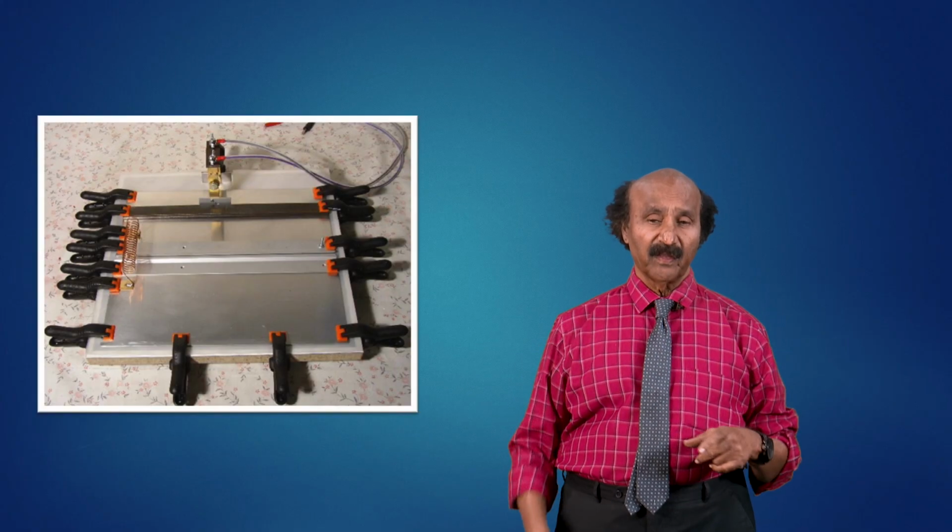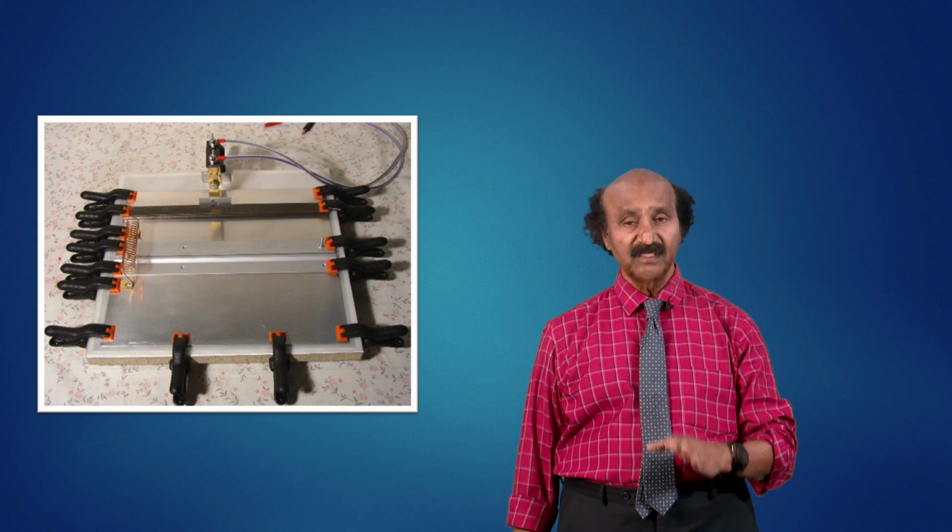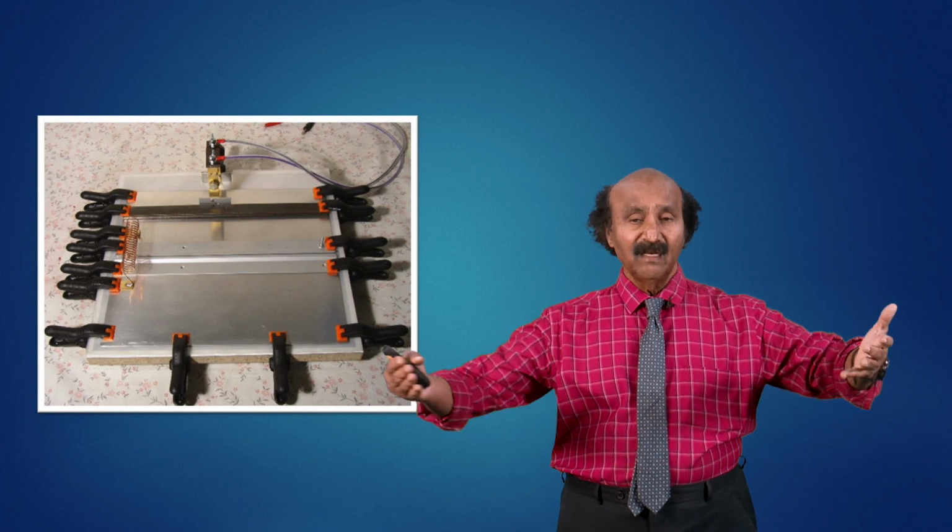You see there are two big sheets. It is true, there are two big sheets. These are thin capacitors. Here is one capacitor, another is a thin capacitor, which is very spread out, very thin. Since they are thin sheets, the inductance of this capacitor is very low. Because of this, when you produce a discharge, the current rise will be very fast. It will go from 0 to maximum within about 10 nanoseconds.